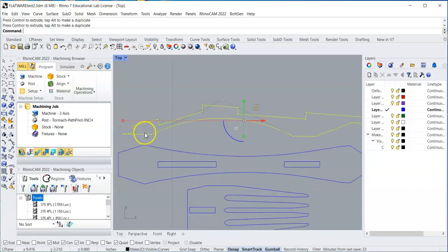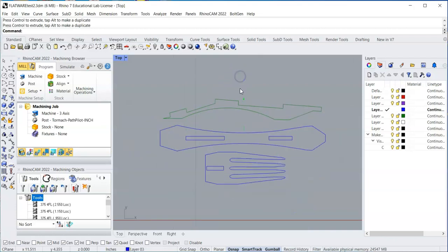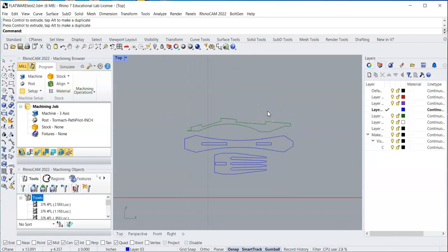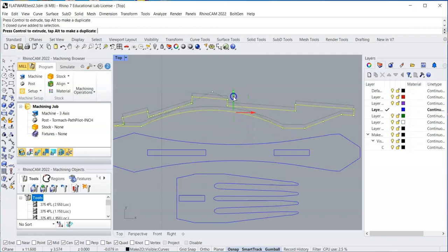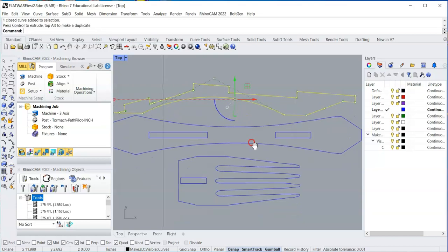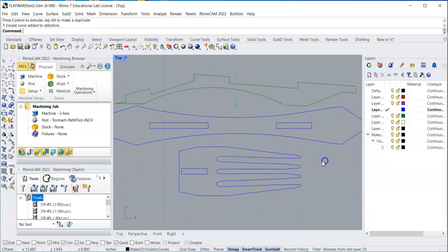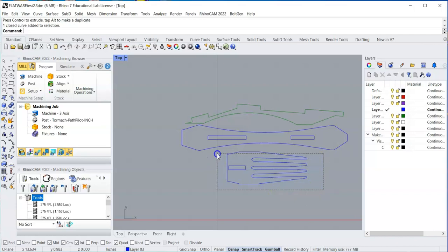Now, we don't want to get too close because we have to run an end mill through here, right? Remember, this is the thing that Evelyn was talking about last class. If you're sending this to SendCutSend, you have to decide. You might want to try uploading one piece at a time so that they can nest them more accurately, or you might say, well, I'll upload just my fork parts, but I'm going to nest them pretty tight. With a laser, you could have these pretty darn close, okay? So just pay close attention to how you're setting these up.